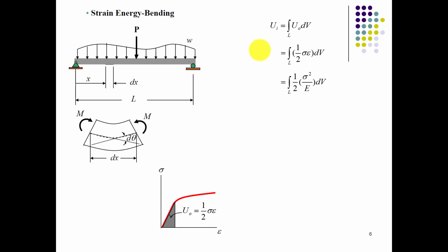Then we will replace this stress with the stress value in the flexural formula that we have calculated in mechanics of solids, which was derived from the hypothetical curvature of bending, and comes out as stress equals My over I. Flexural stress equals My over I, where M is the moment, y is the distance from the neutral axis to the extreme fiber, and I is the moment of inertia of that cross section.